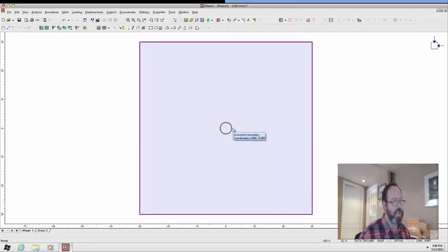Okay, so you can see that we're about 7 diameters away from the tunnel. And so in that way, the tunnel boundary, which is an artificial boundary, represents an artificial truncation of the true geomechanical extents. In other words, the rock really goes on forever, but we're going to truncate it so that we only have to simulate a minimum area necessary to get an accurate solution without having to have so many zones and such a large model that it takes forever to solve.